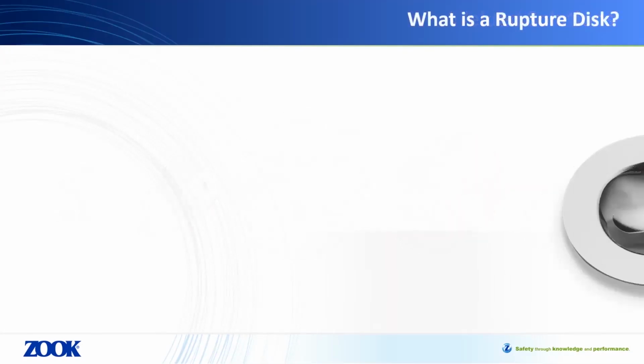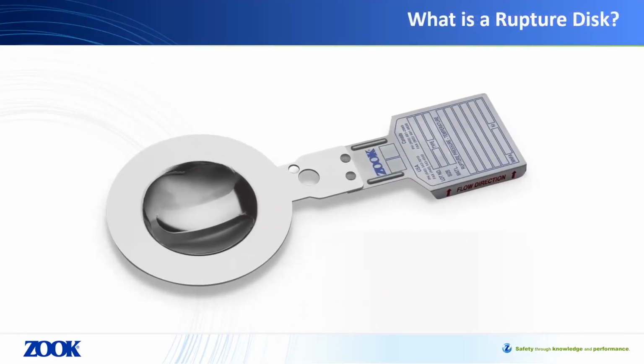So what is a rupture disc? Let's start from the ground up. At its simplest form, a rupture disc is a safety device. To be more specific, it's a pressure relief safety device. As many of you will be aware, overpressure protection is critical in industry to protect plants, personnel, and equipment from unplanned or unexpected overpressure events. In many applications, they're required as part of general system safety.